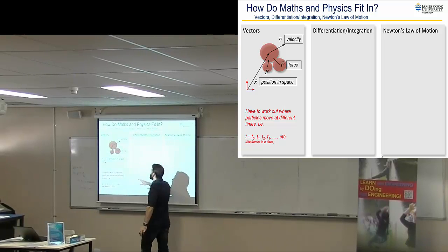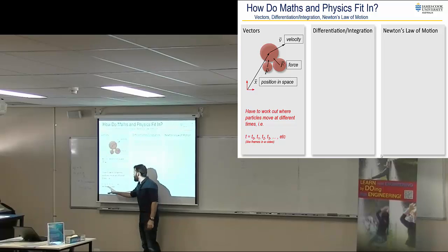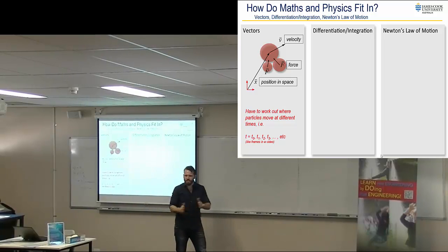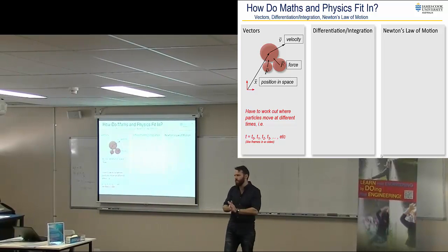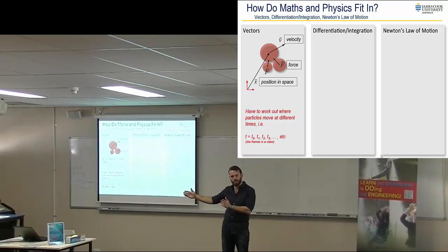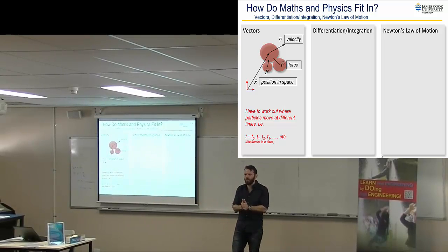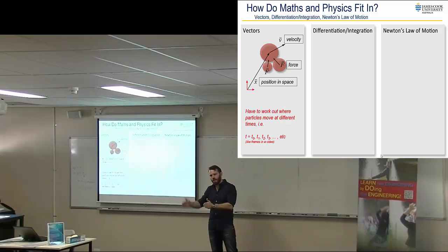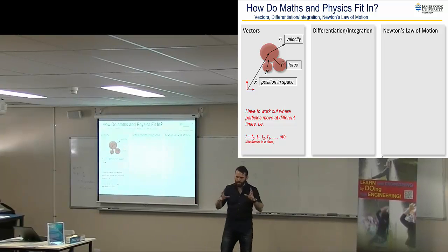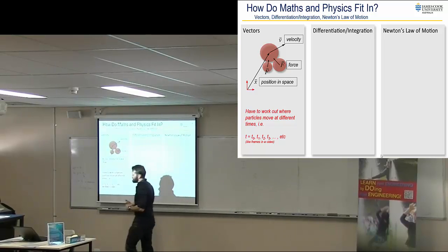We have to work out how these vectors change over time. We can't have a continuum of time, because you can't calculate something in a continuum sense on a computer. So we break time up into small steps. At the current step, we calculate what everything is. Then we say, in maybe 0.1 of a second or 0.01 of a second, what's everything again? We illustrate it much like the way that a video works in frames.